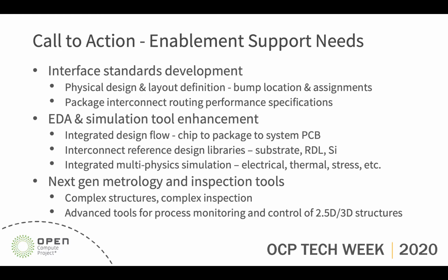And this will require the involvement and support of the EDA community in order to enable the true co-design and verification of these heterogeneously integrated structures. And then lastly, to support the manufacture of these highly integrated and highly interconnected structures, there's also a growing need for advanced metrology and inspection tools to monitor and control the assembly processes.